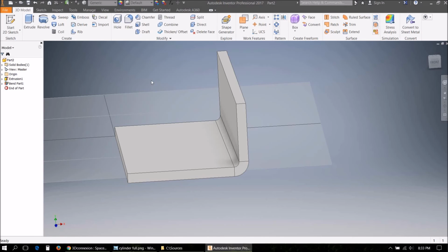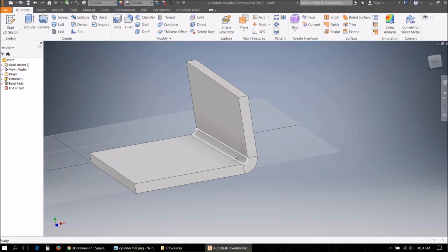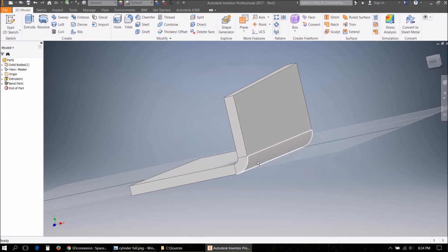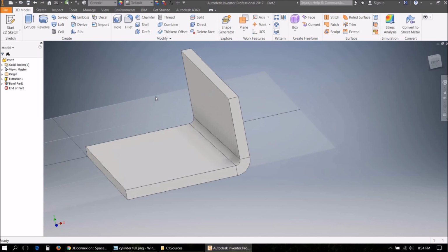Because normally when you create a low resolution model, you just delete features from the feature tree, and that's it. So you create a high resolution model, delete and then copy it. I will show how that's done later on, but with the low resolution model, just go through the feature tree and you delete everything, all the surface detail basically. So all the things which can be replaced with a texture. Now, if you want to reduce these rounded edges here, because they can be replaced with a normal texture, that really cannot be done now, because there's nothing to delete in the feature tree.